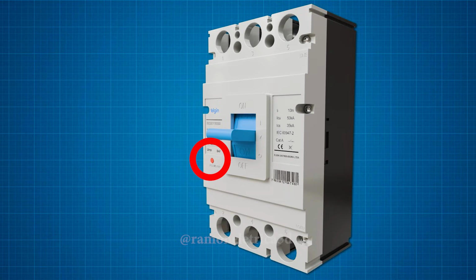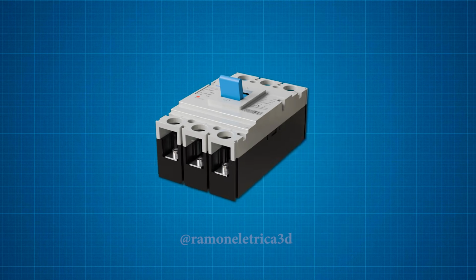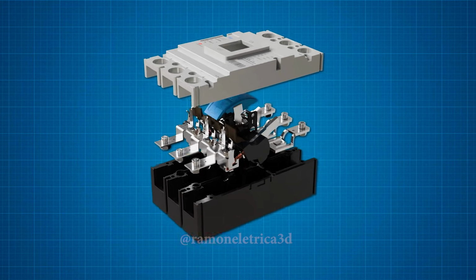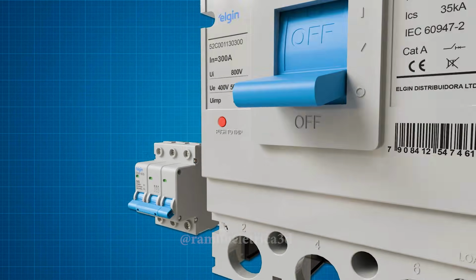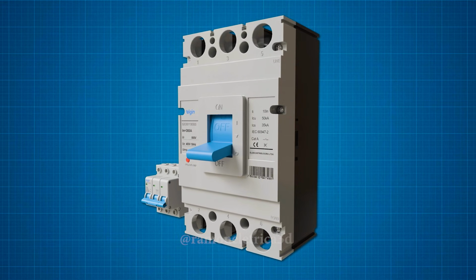In addition, MCCBs have a test button. When pressed, it checks the mechanism and the handle also moves to the center position. With the rated current and short circuit capacity of an MCCB, it becomes clear that choosing between an MCB and an MCCB depends on these values and on the requirements of the electrical installation.